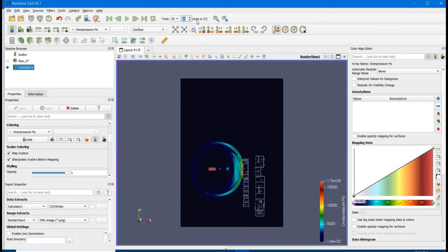There is a slight pressure rise due to the reflection of the shock, so you start to see a bit of red here, higher than 0.1 bar, about 0.15 bar. And finally at 27, that's the last calculation. We could have run it more, and it looks at the issue of the buildings behind.